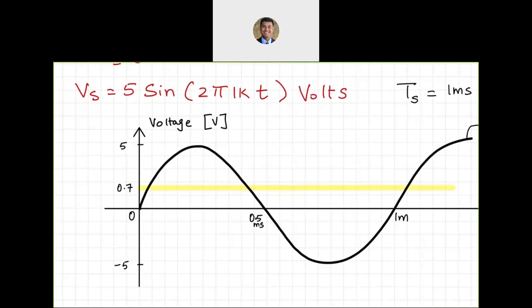So I'm going to sketch the voltage across the diode in, let's pick green for that. So I'm going to have all of that region follow the source. At 0.7, it will not go beyond that, so it'll flatten out there, and then as it comes down, it will follow the source. Now what is going to happen when it goes negative?